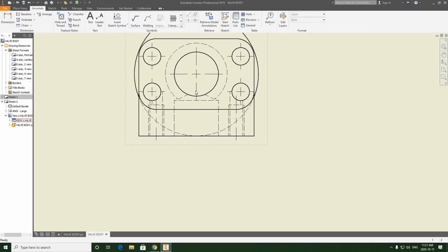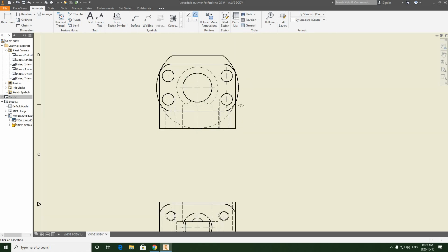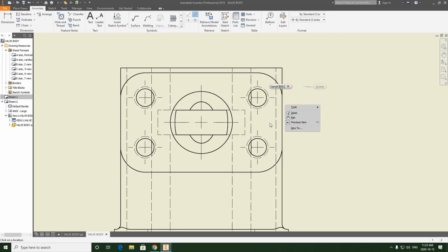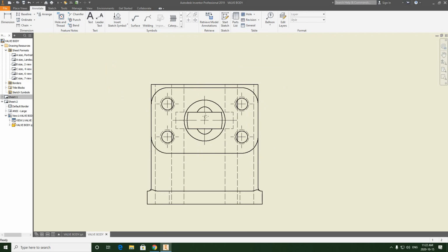And then we have to do the same thing here, right? But if I stretch that one all the way down, it doesn't look like a center line. So what I'm going to do is just create another bisector one here and here. And that's going to give me that intermittent dash. And because this is a blind hole in the middle, this should be stretched out a little further to indicate that this is a cylindrical object in the middle here, right?